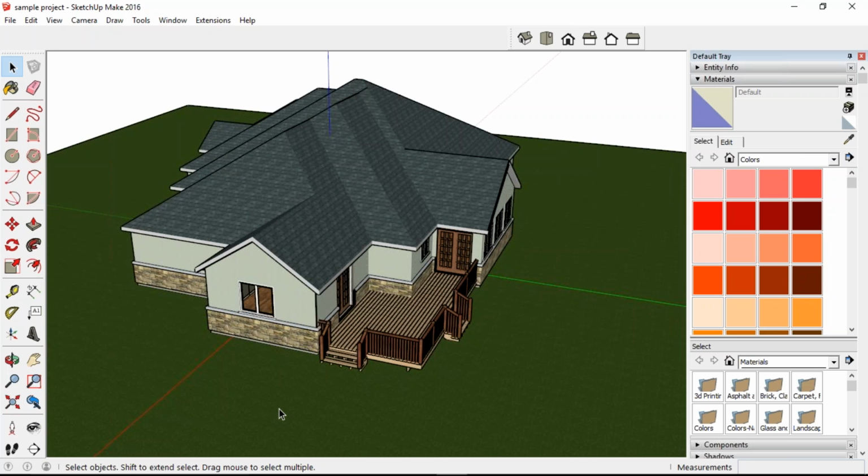You could isolate all those objects by turning everything else off, and then when you export that 3D model, you can export it to that SKP format that you can then bring back in to Envisioneer as one full block rather than multiple pieces. So that's another handy option for being able to export options from Envisioneer to the SKP file format.